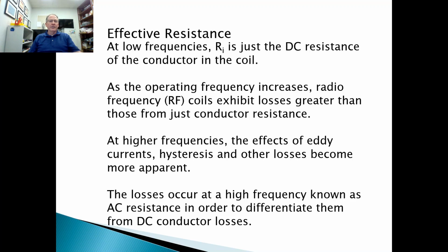All right. Now at low frequencies, the internal resistance is just the DC resistance of the conductor in the coil. And then as the frequency increases, the RF coils exhibit losses greater than those from the conductor resistance. And then at higher frequencies, the effects of eddy current, hysteresis, and other losses become more apparent. So losses that occur at high frequency are known as AC resistance in order to differentiate them from DC conductor losses.